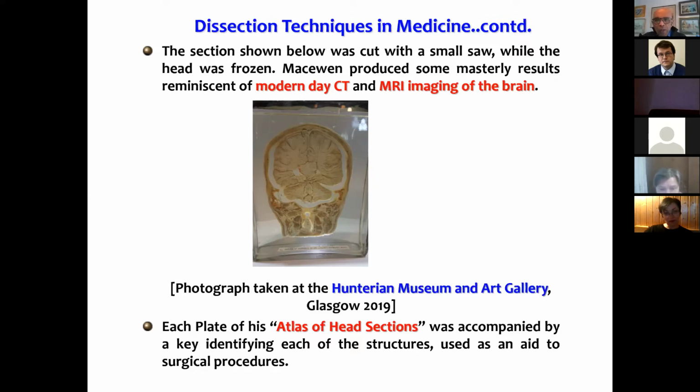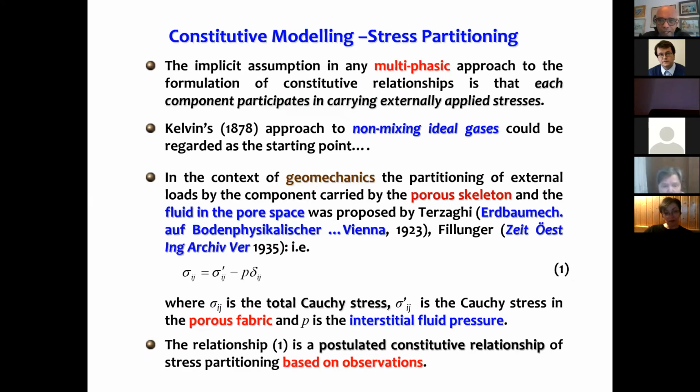So going to the multiphasic part of the behavior of this fluid saturated elastic medium, the important thing to note is that there's a fluid pressure developing in the pore space. The solid material, the porous tissue, also takes some stress. So the externally applied stress is partitioned into these two. So this is really a fundamental concept in multiphasic materials.